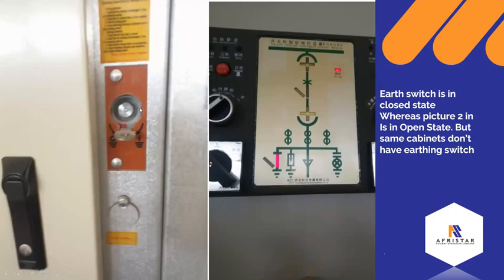Also in the high voltage room, we have an earth switch. If you want to operate on the high voltage cabinet, you must turn this switch on so that the excess voltage is grounded. So this is the point you will come with your tool and turn it on. At this point, we have an LED color to indicate it's open, and on this high voltage cabinet display, we can also see it's turned on.